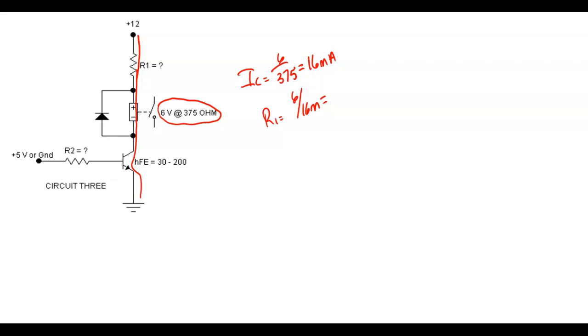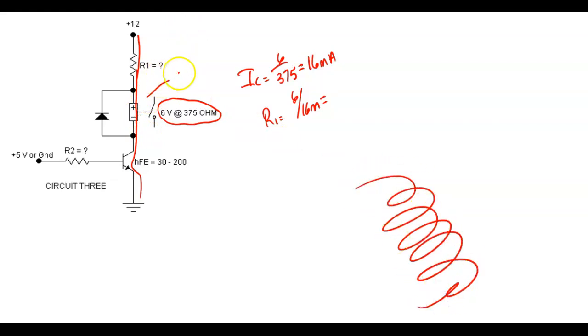Oh, this is a side question. With the battery facing up, and we got... This is not a battery, this is a relay coil. That's what I talked about. This is the symbol for this coil of wire right there. This is what we call the international standard symbol. And over here we use what we call ANSI symbols, which is the national standard. So if you take motor control, which is a really good class, this symbol and this symbol are the same. So this is the international standard.